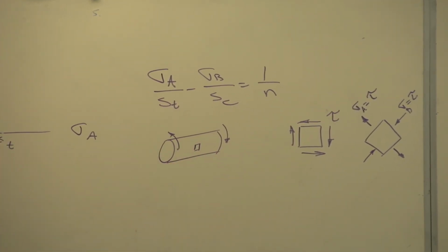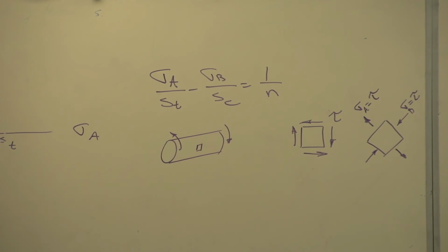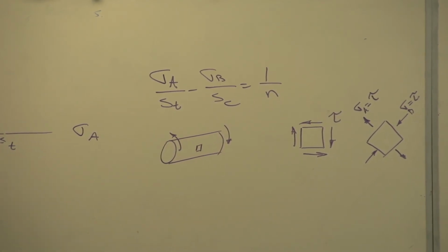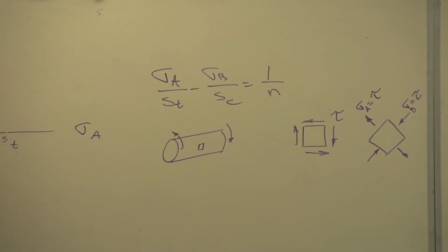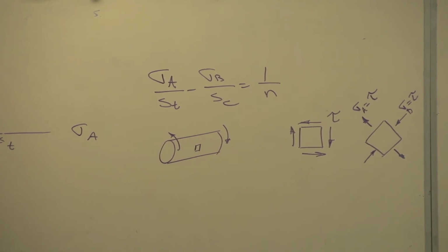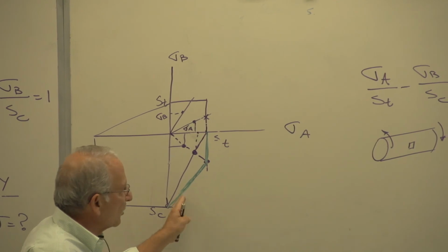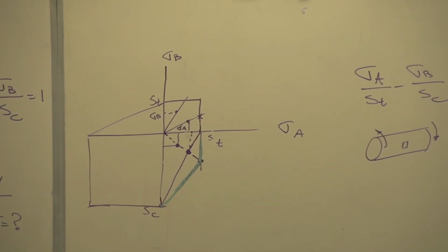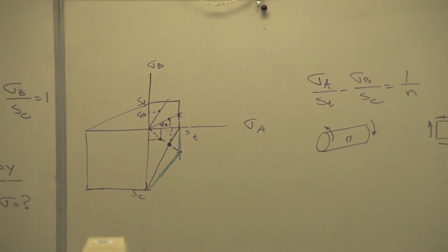We also have the part over here and over here in the modified Mohr line. This was for the Coulomb-Mohr. For the modified Mohr, this is just St over sigma A. And this one, you do exactly the same thing. You solve this equation, write the equation of the load line, put them together, and come up with the factor of safety. And that will give you this equation, which is a little bit more long and drawn out than the other one.